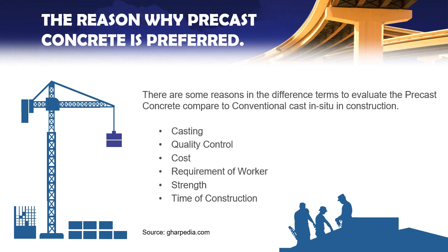Next, requirement of workers and machinery. Precast concrete requires less labor, and only a small amount of skilled labor is required at the construction site. While for conventional cast in situ, more labor and skilled labor are required at the construction site.